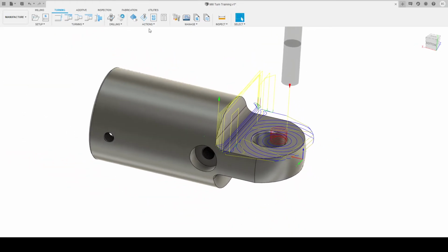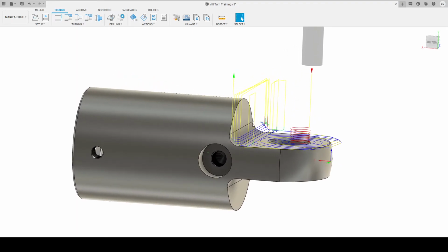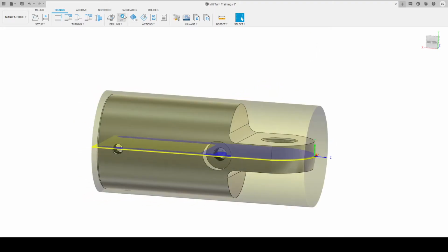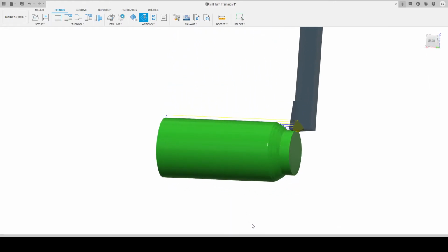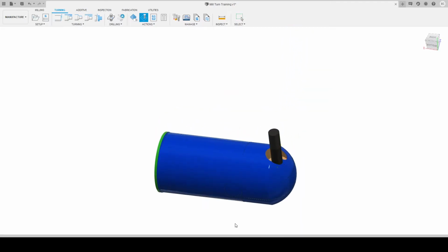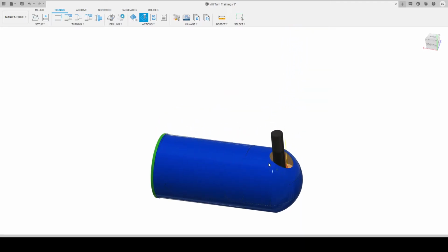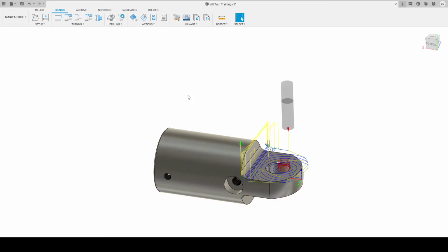So this toolpath is okay, but what it's doing is we're only looking from the top to the bottom. So if we simulate this, it is going to crash. I'll just run through this a bit more. All good, finished. So now we've just plunged in, snapped our cutter, and we're going to start helixing in. Not an ideal toolpath.